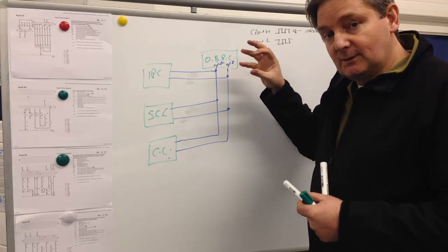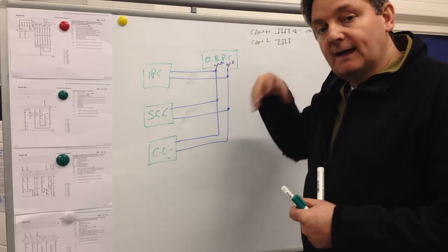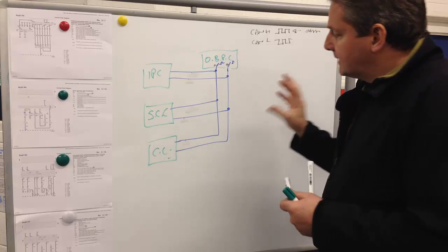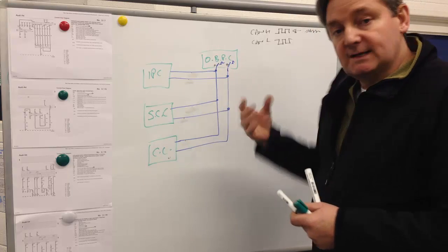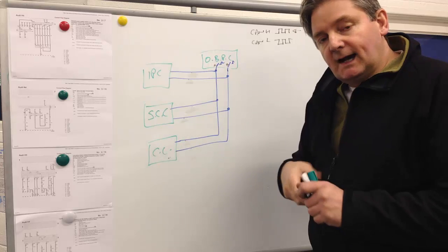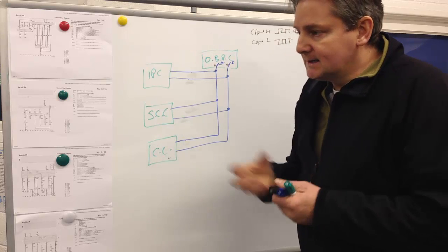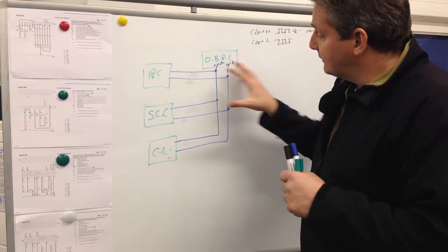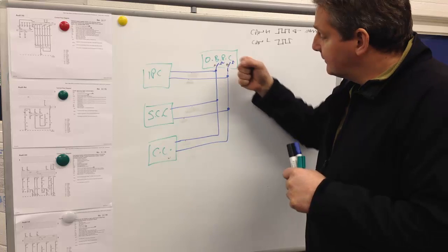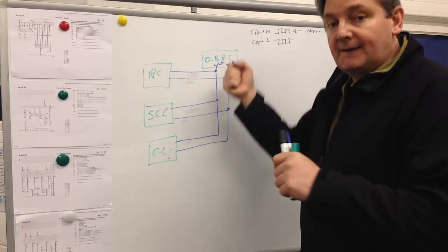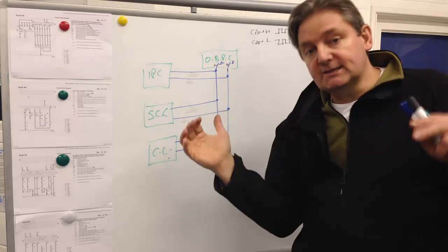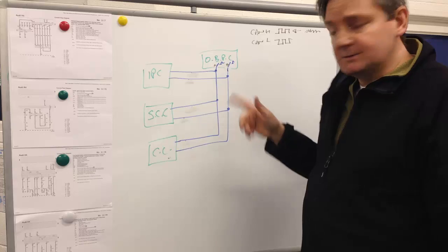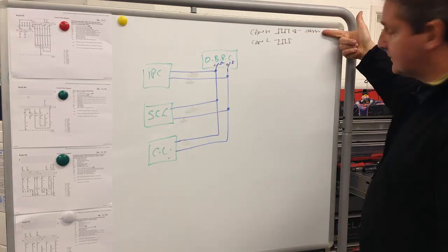If that's the case, we need a new module, and that onboard power supply control unit will then enable the network to start talking. But the second thing we have to consider is the way the wiring loom is under the car. It's quite a tight connection, and so what we're thinking it could be is when we disconnect that plug and pull it down, the wiring loom is actually moving. So if we have a short somewhere in the wiring loom, the flex of us disconnecting and then reconnecting, making the wiring loom go from a rest to a relaxed position, is actually what's causing the difference between our good waveform and our bad waveform.